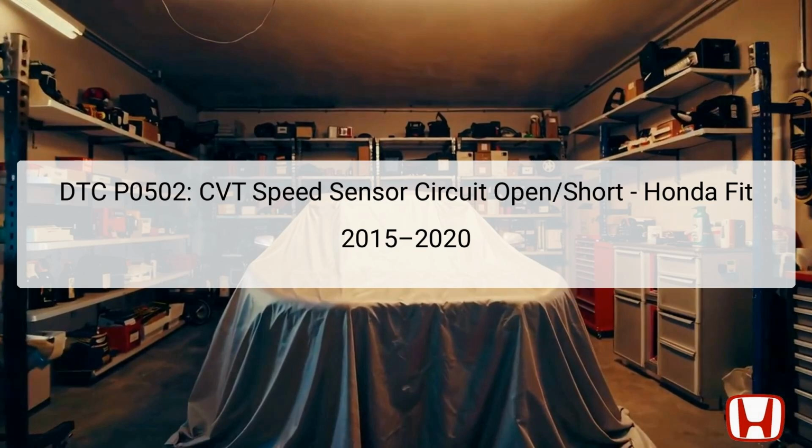The CVT speed sensor itself plays a crucial role in monitoring the rotational speed of the transmission fluid, sending necessary signals to the powertrain control module, PCM, for optimal functionality. Problems at this level can lead to poor vehicle performance, as the PCM relies on accurate data for smooth gear transitions. Identifying this code requires systematic troubleshooting, aimed at the electrical connections and wiring that facilitate communication between the CVT speed sensor and the PCM.